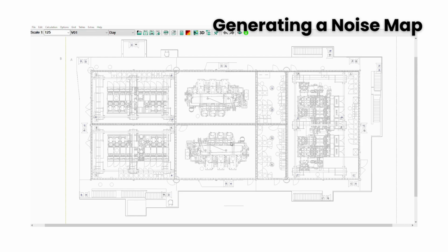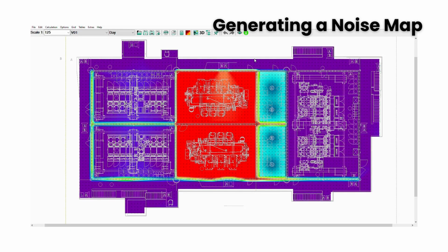The noise measurement can only be established on industrial plants if all machines and installations are in operation. The software calculation can only be executed if the data of all machines, buildings, structures, etc. is available. A typical noise map looks like this one. We can see different kinds of noise sources: surface, point and/or line source. Different colors mean different noise levels.